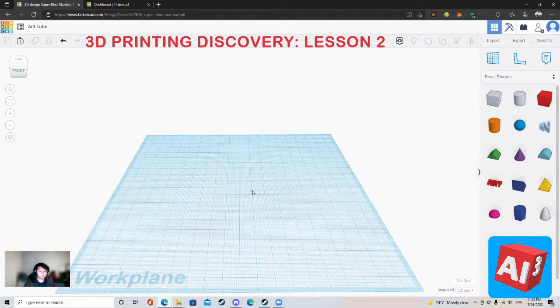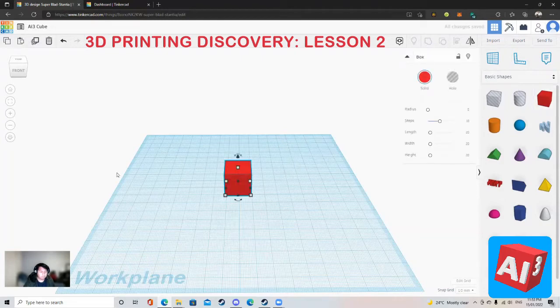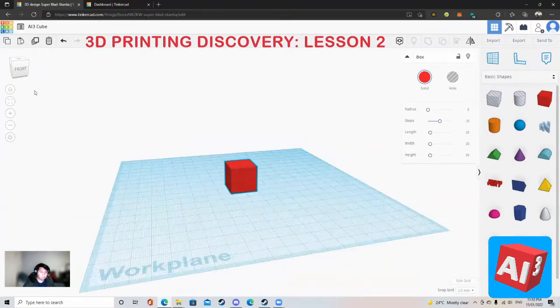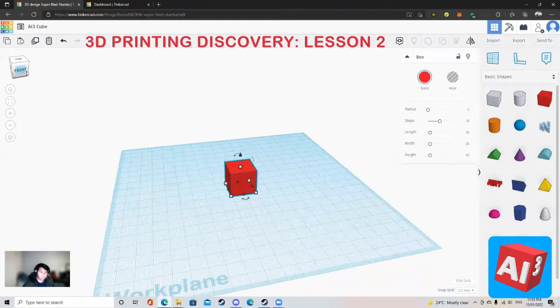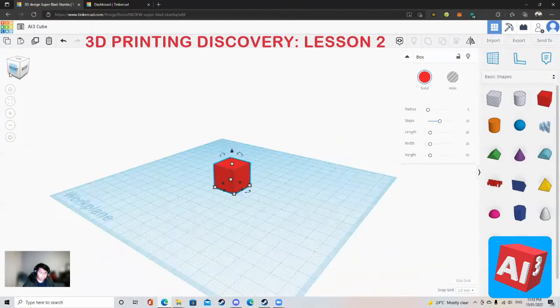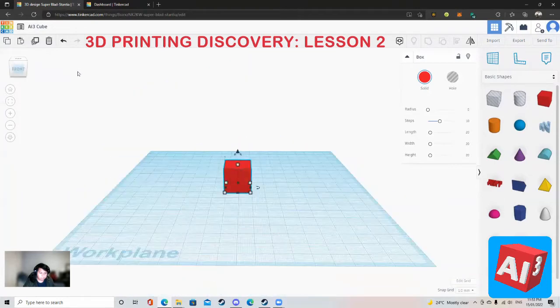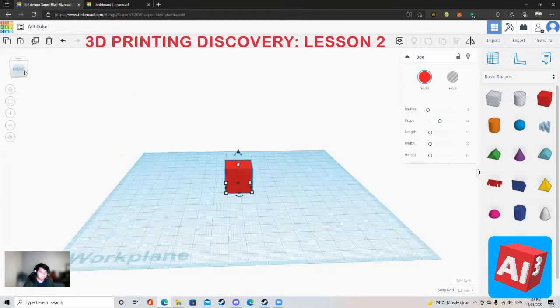There are 2 ways to actually control the camera. First, what I'm going to do is put in the cube first, and I'll show you how to control the camera. The first way to control the camera is by pressing the right mouse button and just dragging around like this, or you can just simply click this cube up here and then click around to move around, to rotate your camera 360 degrees like this, up and down.